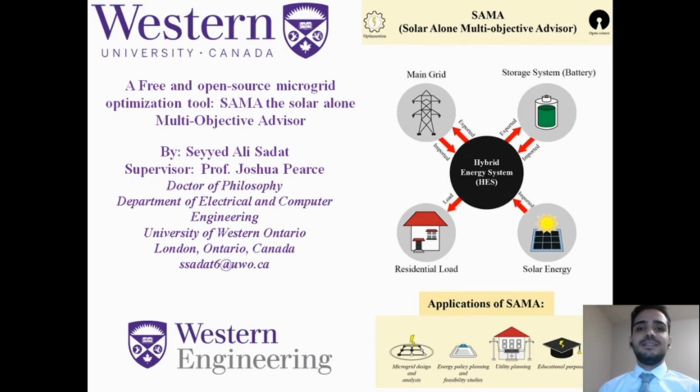This software package is a free and open source energy system optimizer and analyzer mainly concentrated on off-grid photovoltaic renewable energy systems. Using SAMA, users can find the optimum size of a hybrid energy system for their property based on the electric load data and meteorological data such as temperature, irradiation, and wind speed. Users are also able to access the economic data for their optimum system based on SAMA calculations and optimization.